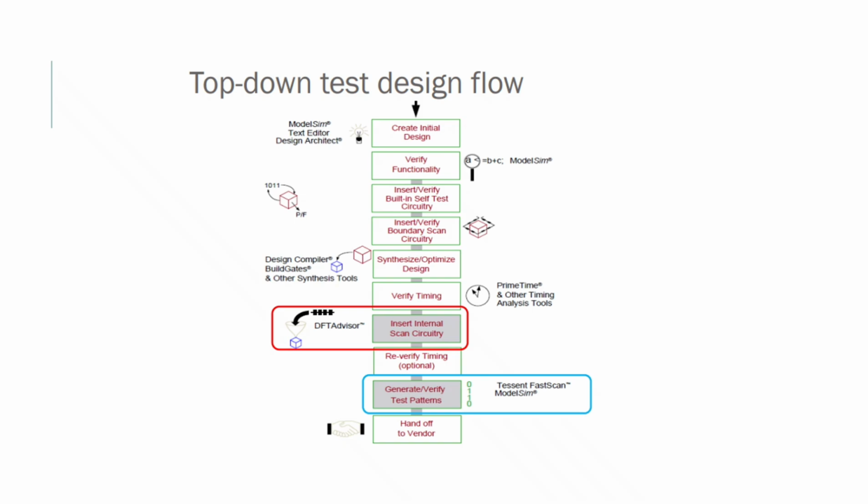Other than scan, ATPG and simulation activities, it is also important to understand MBIST, which handles the memories, LBIST, which handles the logic, and BIST for the logic instead of scan in a few scenarios. OCCs have to be taken care of.